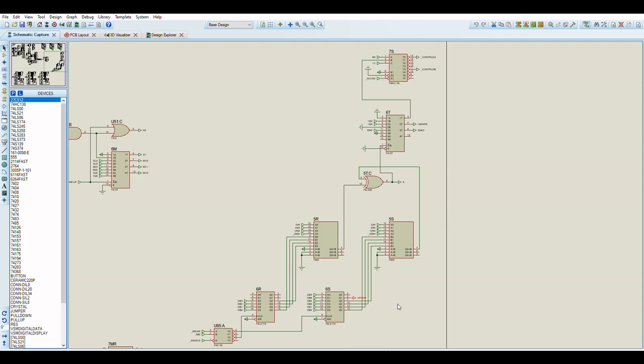And this means that during the visible portion of the screen, if I would write to the Sprite RAM registers, there would be contention because it's trying to read from the RAM as I'm writing to the RAM. And when it reads, it was reading all sorts of random data. It's not random data, it's actually data that exists on the memory bus at the precise point when I'm trying to write to the memory. So this contention was visible in the simulated video hardware as different colored pixels, not the Sprite data that I wanted to see.